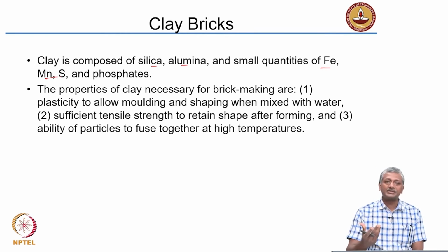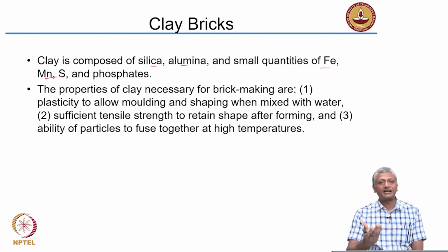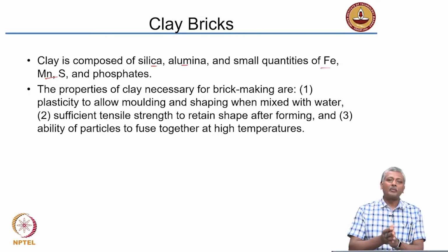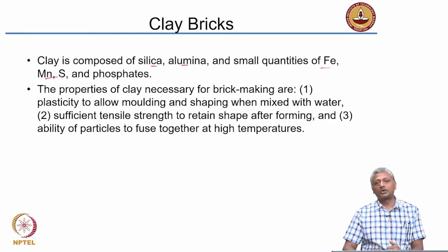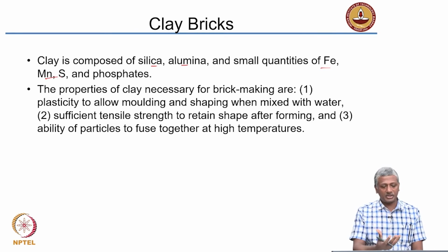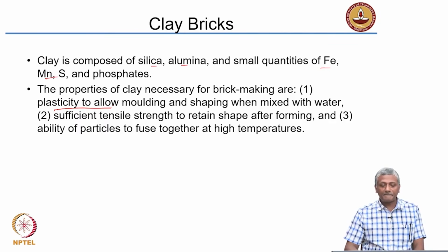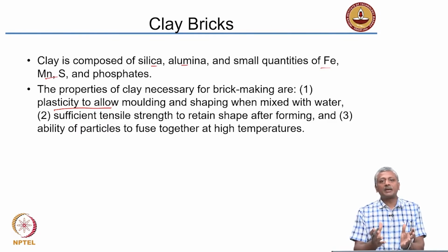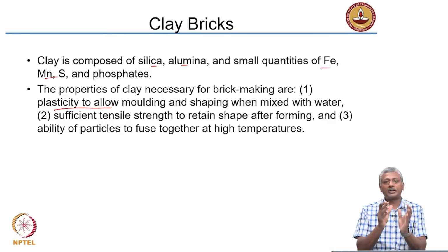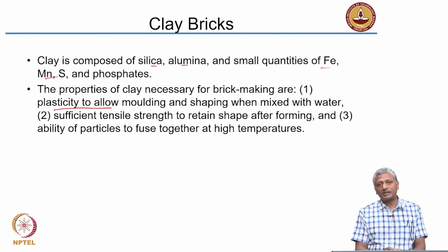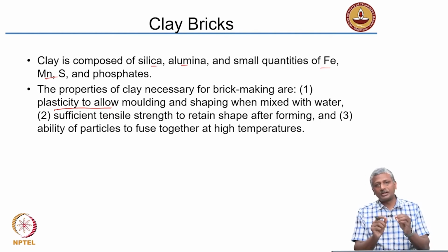Now, what do we do with this? Clay, as you all know, you played with clay as children. When you mix it with water, it has a nice pliability or plasticity. So you can actually start forming shapes when you mix the clay with water. So what you need is the plasticity that allows molding, and you need to have the retention capacity of a shape. Supposing you have molded a particular shape, the clay should retain that shape after mixing with the water. So your water content should be just enough so that the clay is able to retain its shape.